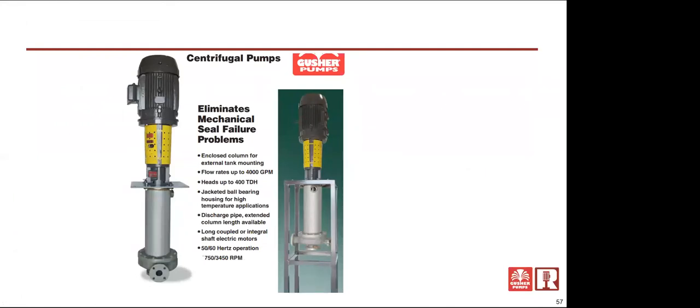One of the things that we're going to be promoting heavily this year, and I hope this whole conversation has not come across as a sales pitch, because it's really not, but this is a cool device that we're going to sell. We're going to focus on marketing this year, focus concentration on. What this is, is a vertical sealless pump. And remember I said that seals are one of the first things that fails in a rotating piece of equipment, the sealing method, because of shaft vibration and stuff like that. Well, this is a sealless pump.